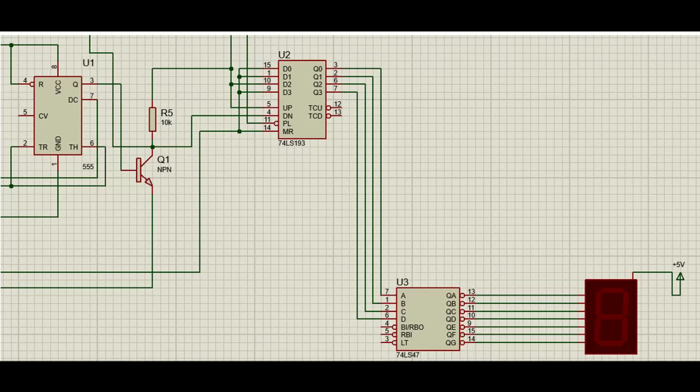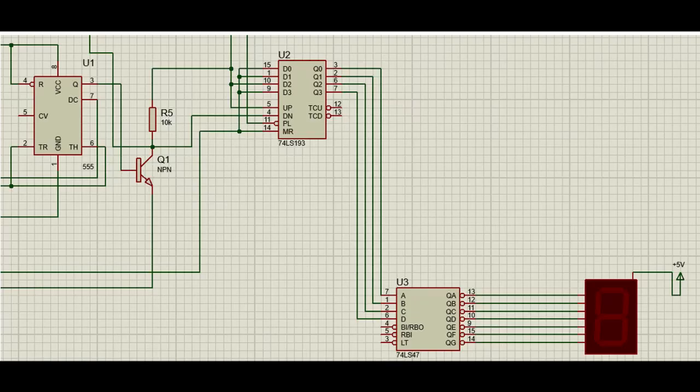It can count both up and down, so we have set it up so it only counts down and thus acts as a timer. The up pin is set on high and the down pin is fed from the 555 timer's output. As previously mentioned, our prototype signals red light for 5 seconds, so after 5 seconds the timer should reset itself. We designed some logic circuitry to detect when 5 seconds pass and to reset our timer. The timer loads the number 5 when not in use, to prepare for the next counting. The pull up pin is used to reset or load the number 5.